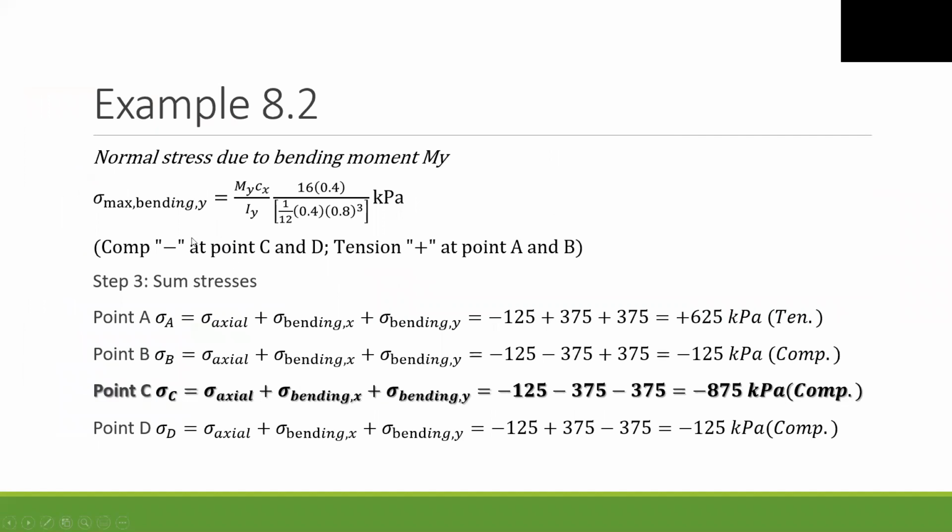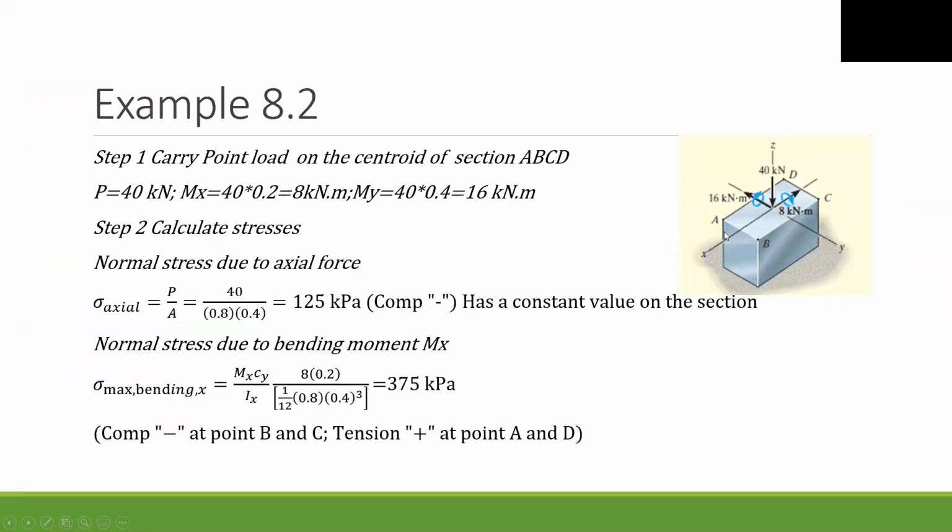Okay. Also on bending Y, we have a position like this, and this moment causes bending for Y bending, and you can see this arrow showing to this side. Therefore, this is the compression side. Okay, and I can use a different color.